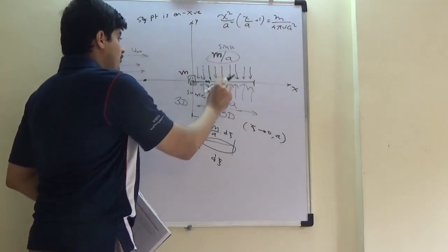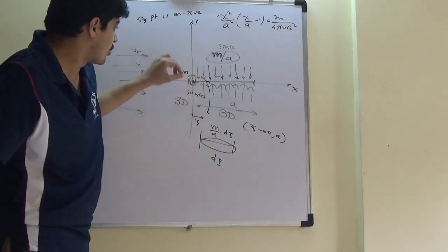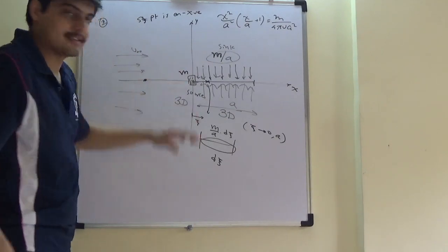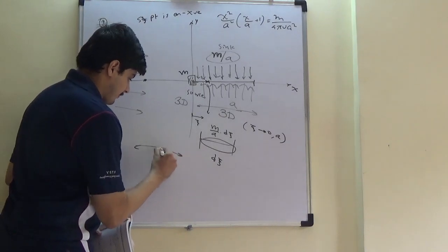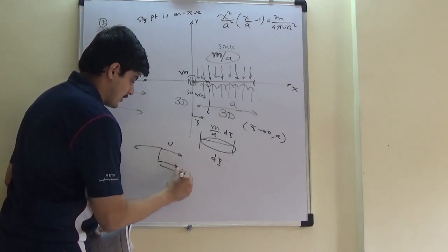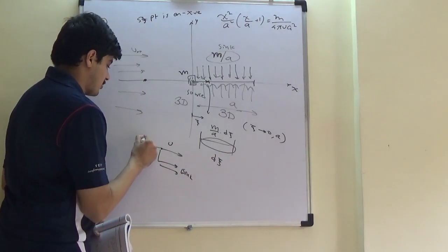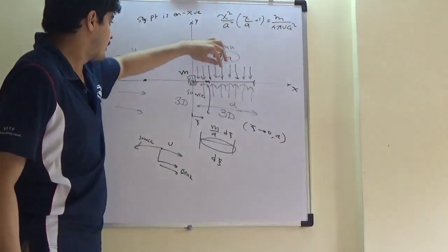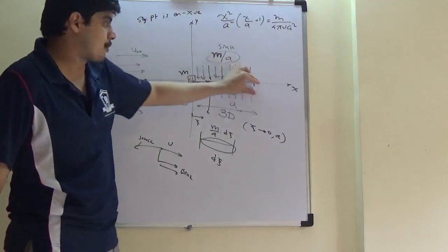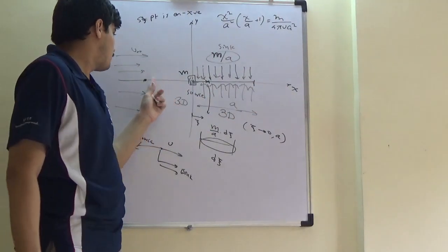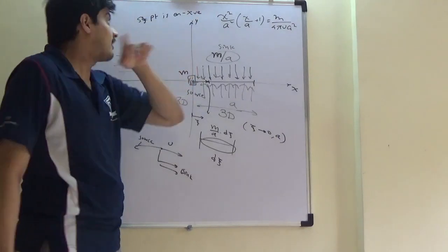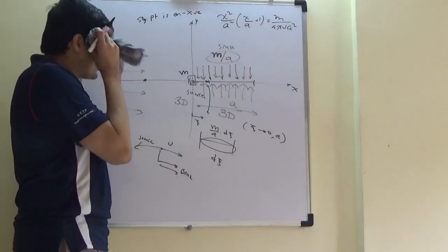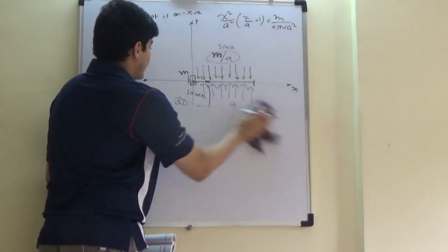So this is independently forming like a doublet, but a complicated doublet. Flow is going out, some portion is sinked in, and then sinked in. So there are two pulling forces, U and sink, and one pushing force, source. Here, everything is in one direction, right? Sink is sucking everything that the source is providing. So a stagnation point is most likely to be on the negative axis, and that's why this is the first step to understand why negative x is the stagnation zone. So now, armed with this physics understanding, let's write this down mathematically.